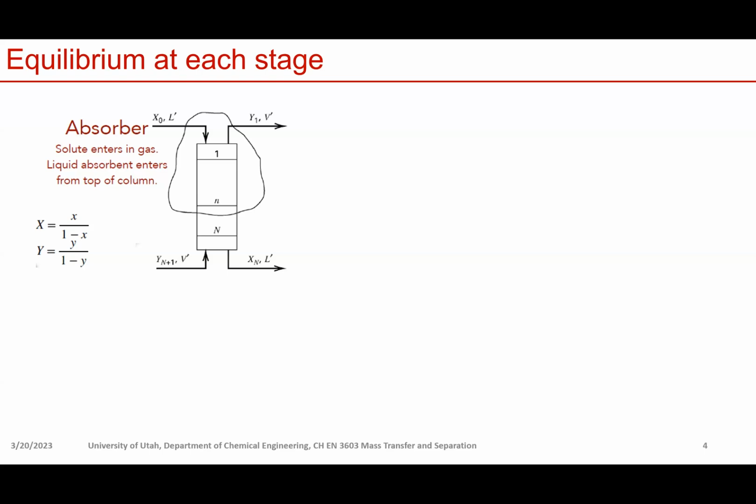Because in that case, the solute will have the maximum chance to be transferred from the gas phase into the liquid absorbent, right? And typically you achieve that if you have very good contact between your liquid stream and gas stream, and with sufficient residence time, right? If they have sufficient time to mix, okay.